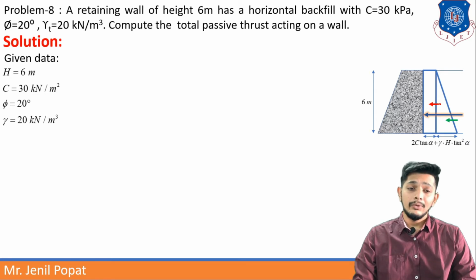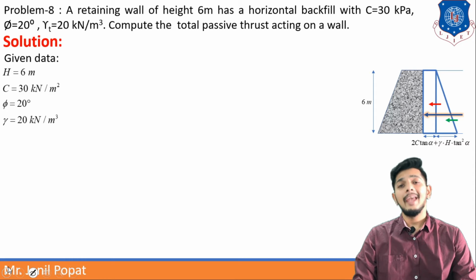Here a red arrow is showing a rectangular pressure force, a green arrow is showing triangular pressure force, and the blue one is the average or mean of both, or total pressure force. In the active earth pressure case we have discussed these types of problems. It will be solved the same way, but some formulas will change.